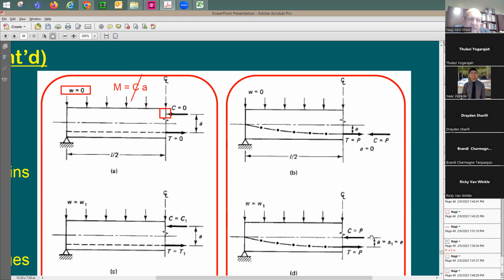The moment arm is going to start to develop because the applied external moment is going to be equal to the internal, and the internal here equals, let's say, T multiplied by this A. The tension or compression force is just constant. So when this is constant and you have this new moment value, it means that A is going to start to grow in value.